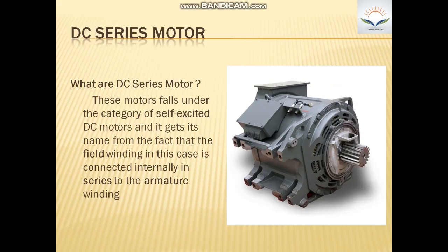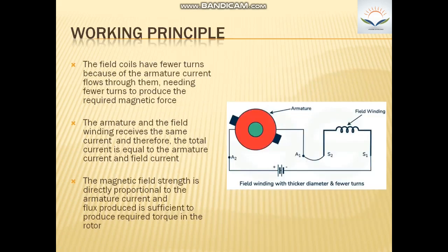DC series motor. These motors fall under the category of self-excited DC motors, and it gets its name from the fact that the field winding in this case is connected internally in series to the armature winding. Let's understand the working principle now.